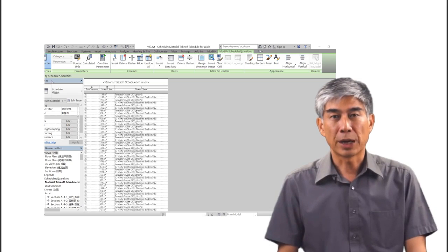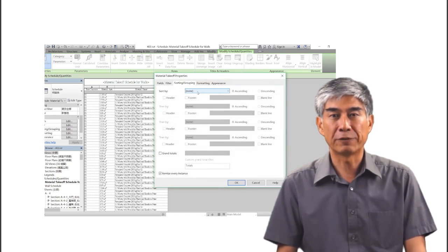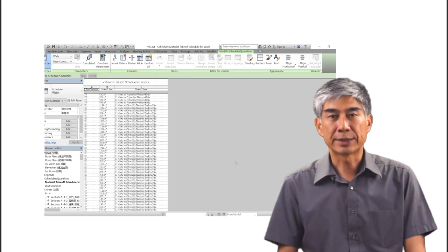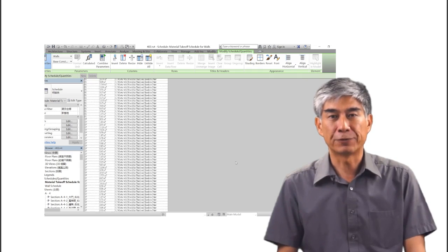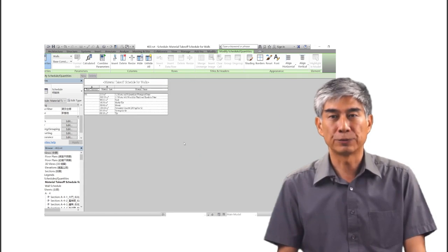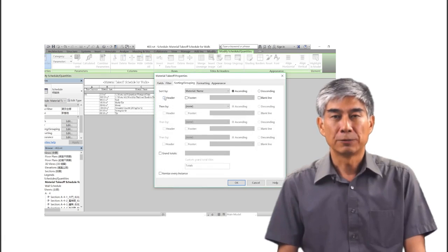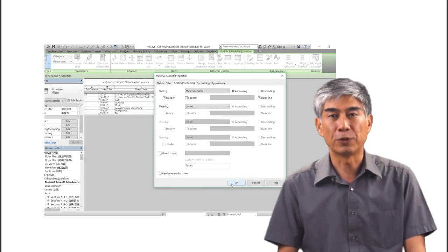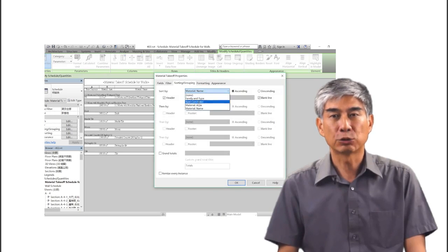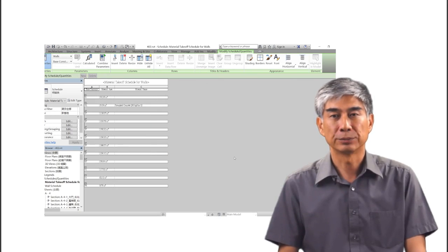In this session, we are going to take a quick look at Revit schedules. Let us go through the 6 schedule types in Revit first. Then I will use the material takeoff schedule for walls in this project as an example for demonstrating how to perform sorting, totaling, and filtering in the schedule and how to export the schedule.